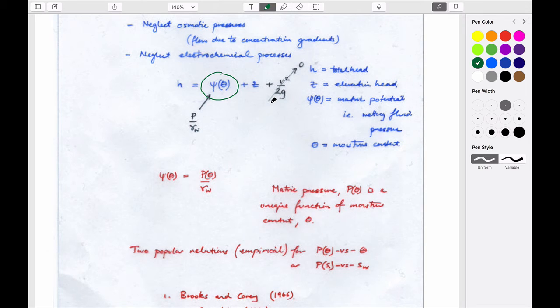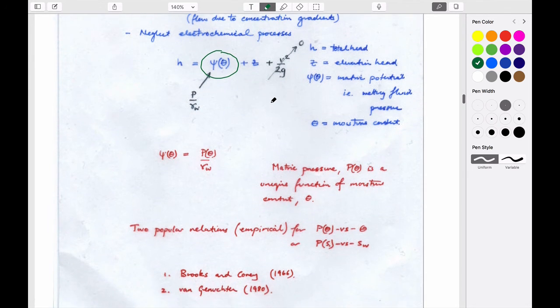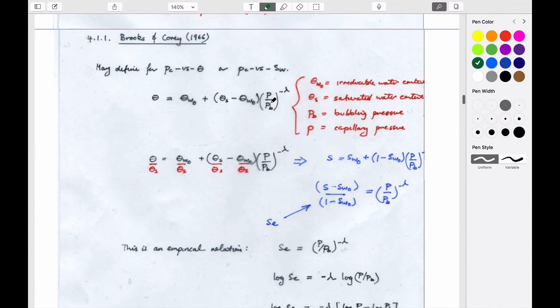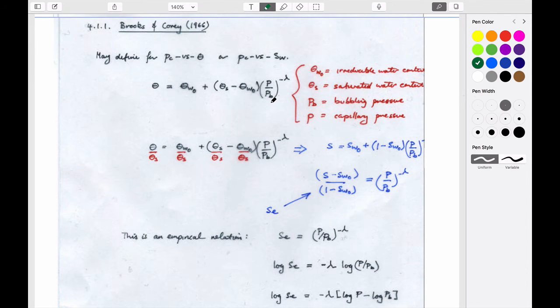And it's important because when we talk about these two fundamental relationships that we're interested in, capillary pressure versus saturation curve and relative permeability curves, we can define those behaviors in terms of capillary pressures, the difference between the pressures in the two phases, air and water for unsaturated flow, or DNAPL or NAPL and water for saturated flow. And we can use certain relationships to define those behaviors. And we've broached one of them already, but let's spend a bit more time looking at it exactly. I think it always behooves us to spend more time on it.